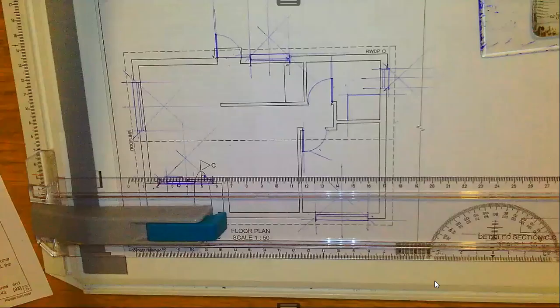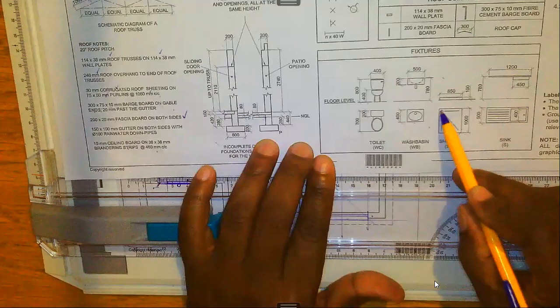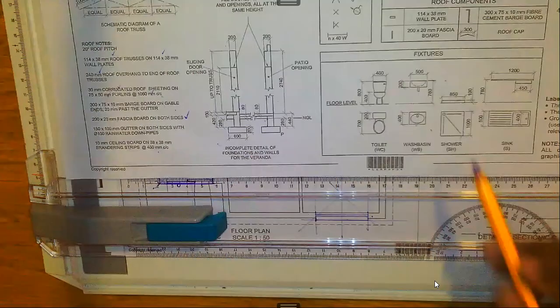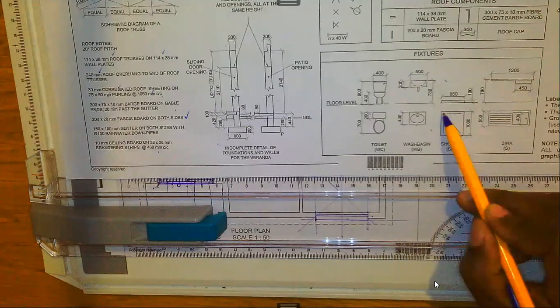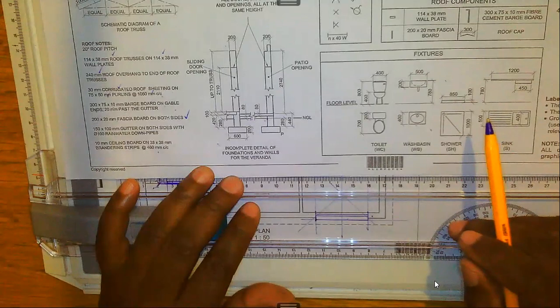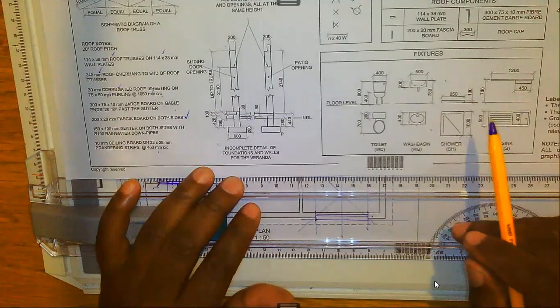Now, what is missing if you check on the top view? There is this part, we refer to this one as the drain. In most cases, the drain is diameter 50. So if you say 50 divided by 50, you get 1 millimeter. It might be difficult to draw 1 millimeter as a diameter. So in situations like that, where you have got very small circles, you can do that freehand.